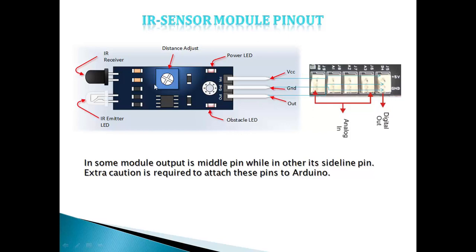So once you are going to connect this IR sensor to the buggy analog input ports, as we have already discussed in the previous lectures, we have four analog input ports in your buggy, that is A0, A1, A2 and A3, right? You can see at the very left, at the very top, we have a 5 volt supply, the last pin is ground, and the center one is your output port.